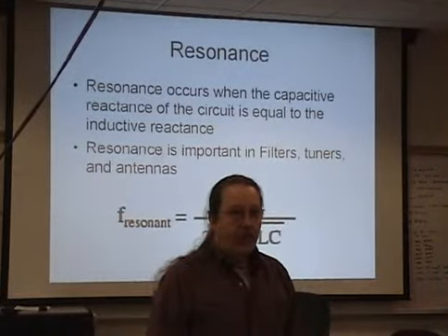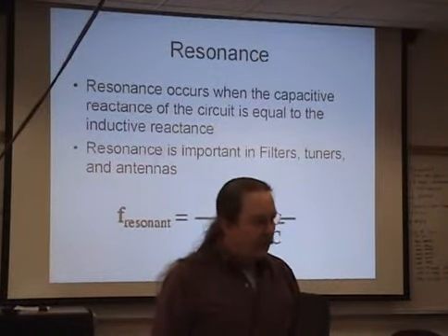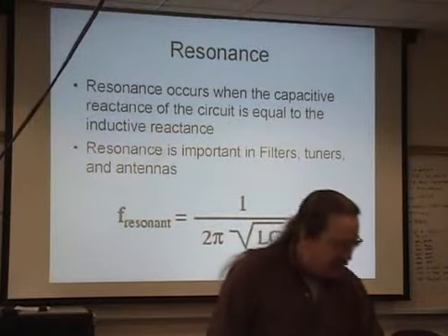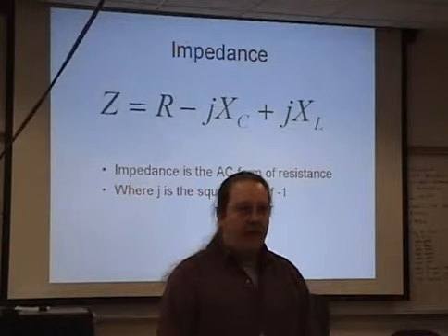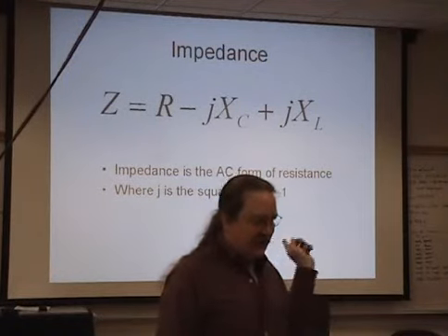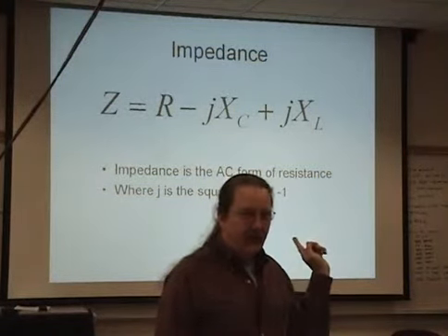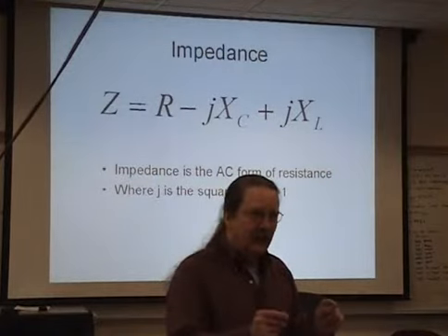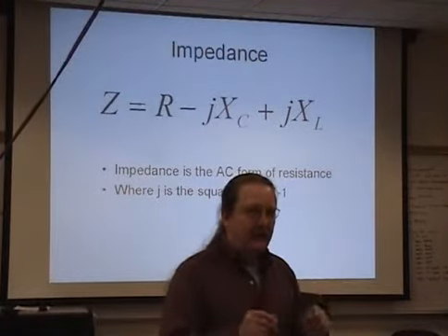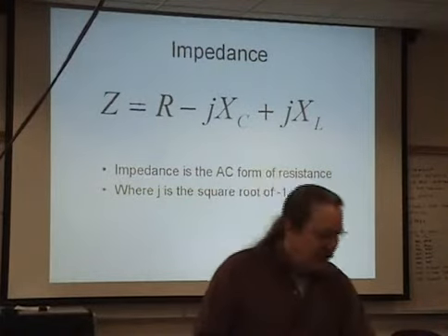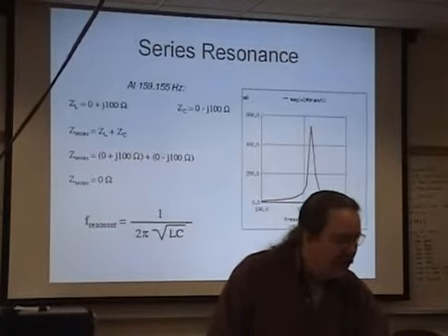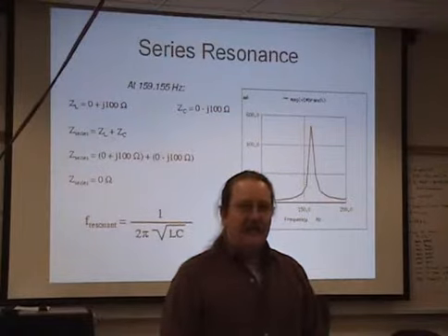Well, it has a broader Q than does a solenoidal inductor, so if you want to have a really high Q, you don't want to use toroids. But modern systems tend to use toroidal inductors because you can get smaller ones to do the inductance for you. Right, you use less wire, they're cheaper, faster, quicker. They wire around a ferrite core or a steel core.